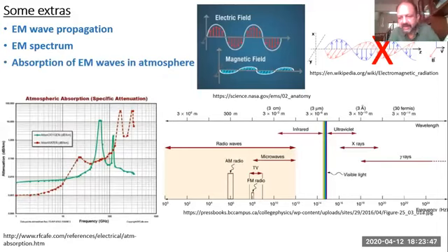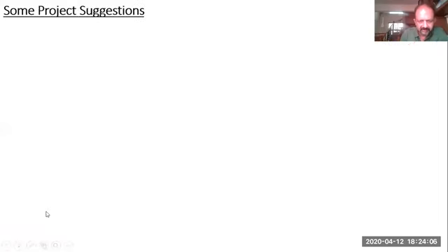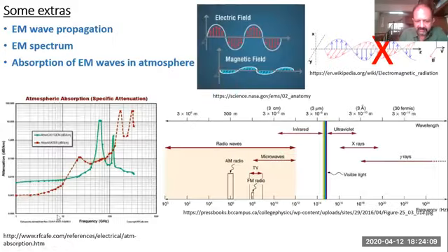This diagram on the left-hand side is very interesting. Somebody from the audience could have asked me, Commander Shishir, why is 77 gigahertz the frequency chosen for the radar of the car? And the answer is right here. What is on the x-axis? The x-axis is the frequency in gigahertz. So this is 10 gigahertz. It's a logarithmic scale, and this is 100 gigahertz. This is the attenuation because of oxygen in the environment. Attenuation of what, ladies and gentlemen? The electromagnetic signal which is going from the radar.